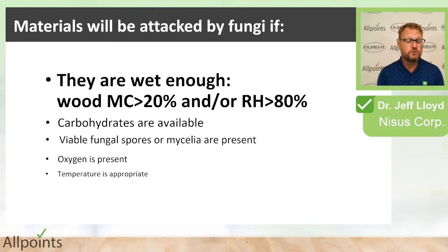And so when you buy kiln-dried lumber from the builder's yard, kiln dried means it's specifically dried to less than 20%, to 19% or less. So that KD stamp on the lumber means 19% or less. So it can't go moldy, it can't support fungal growth. And typically a relative humidity of less than 80% is not going to support fungal growth. Now sometimes if you really crank the AC in a home, you can cause condensation at lower relative humidities than that, and we'll touch on that a little bit. But if you remember, 20% moisture content and 80% relative humidity, those are real good numbers.